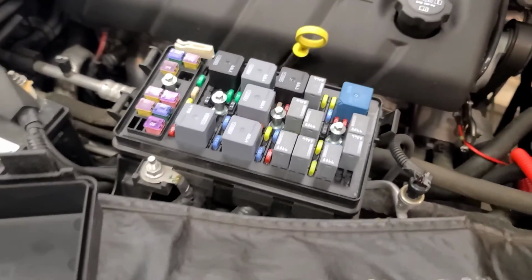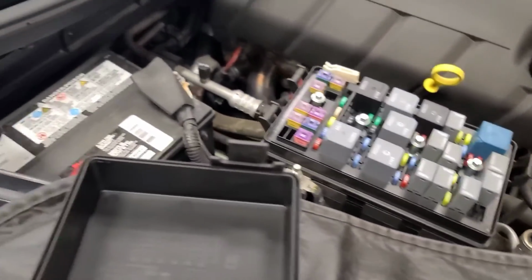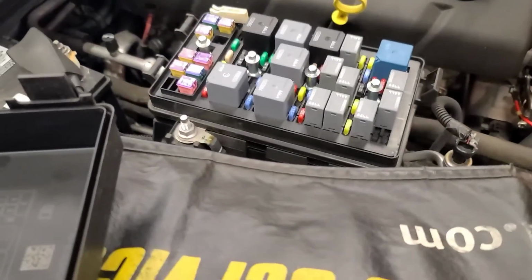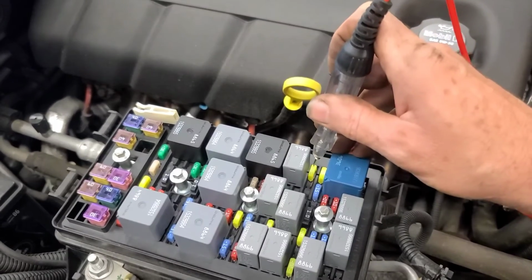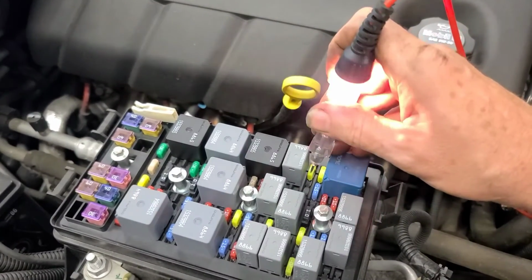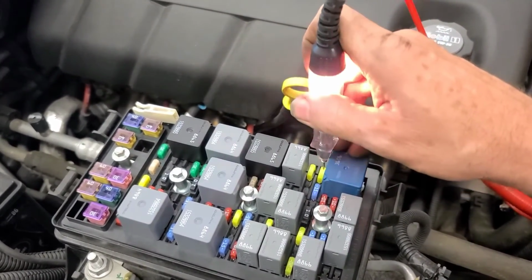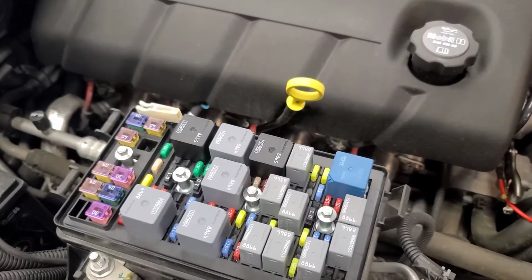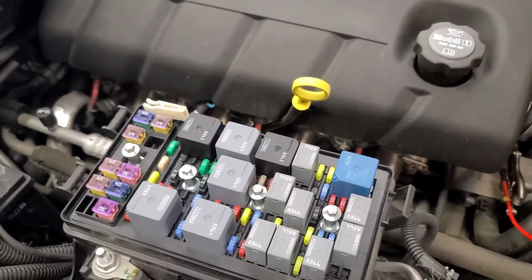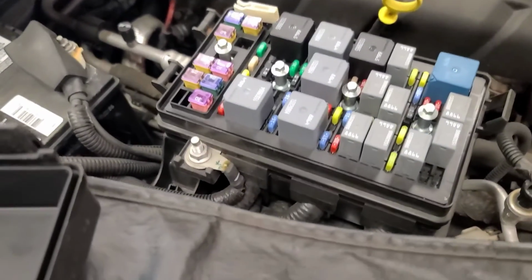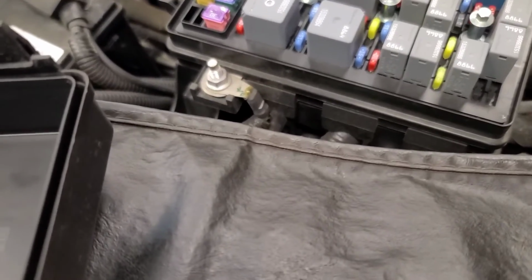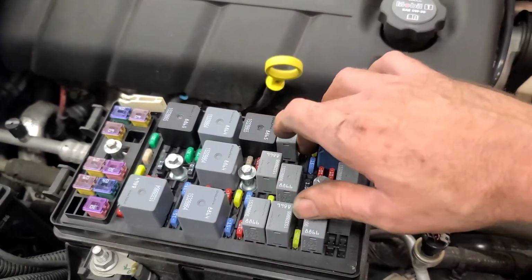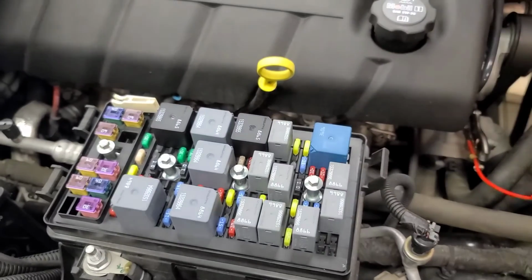But of course the lights have to be on. So we're going to turn the lights on, make sure my test light works. Yes, it does. And test that fuse. Okay, so we got the headlights on, power on that side, power on that side, power on that side, power on that side. So it's not the fuse. Just to be on the safe side, I'm going to pull the fuse out and physically look at it in case one of the terminals is compromised, but this car is like brand new. So the fuse, as I suspected, is pristine. So what we want to find out now is if there's anything between this fuse and that headlight.